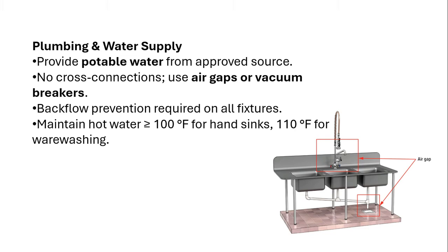Then I turn on the tap on the other side of the kitchen, and that little bit of hose water that seeped its way back into the system is now going through your sink over here. Your sink over here is where you're cleaning your lettuce to go onto a salad, which is ready to eat. See where the problem is here? We're now getting contamination into our water supply because of a cross connection.